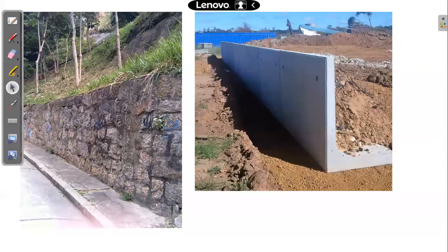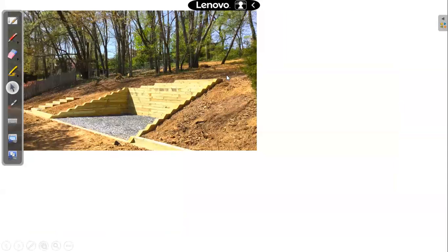And this is one more use of the retaining wall. Maybe sometimes we may require such elevation difference to be maintained on the ground surface. So there also we require to have the retaining wall, maybe a masonry retaining wall, or it may be a reinforced concrete retaining wall. Nowadays we also come across precast panels, earth panels, which also act as a retaining wall.